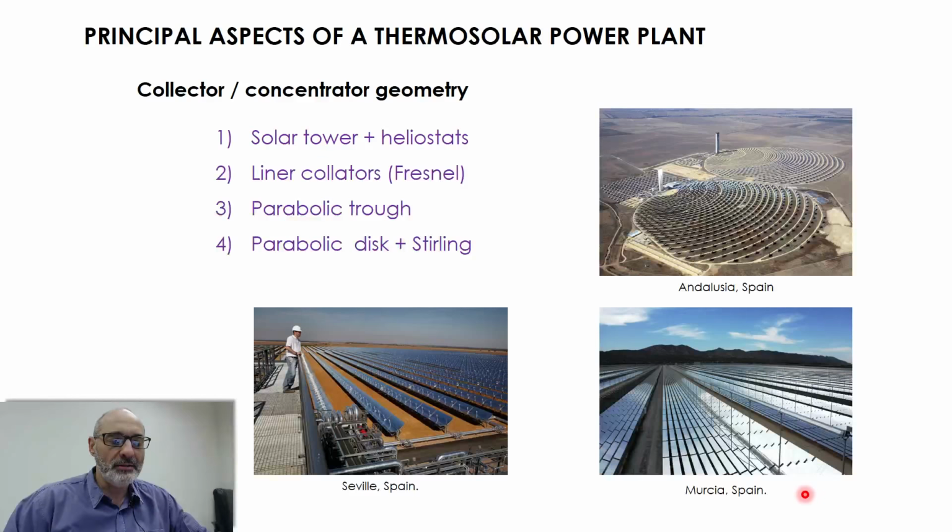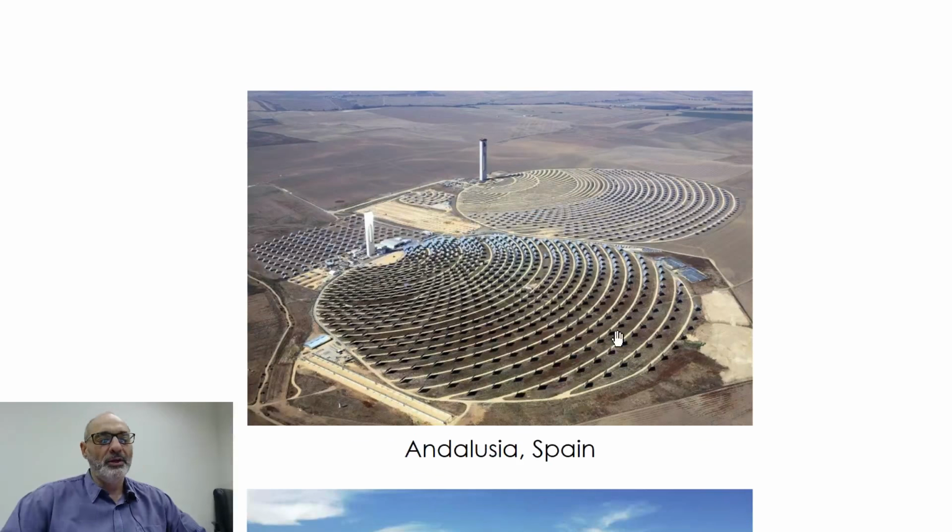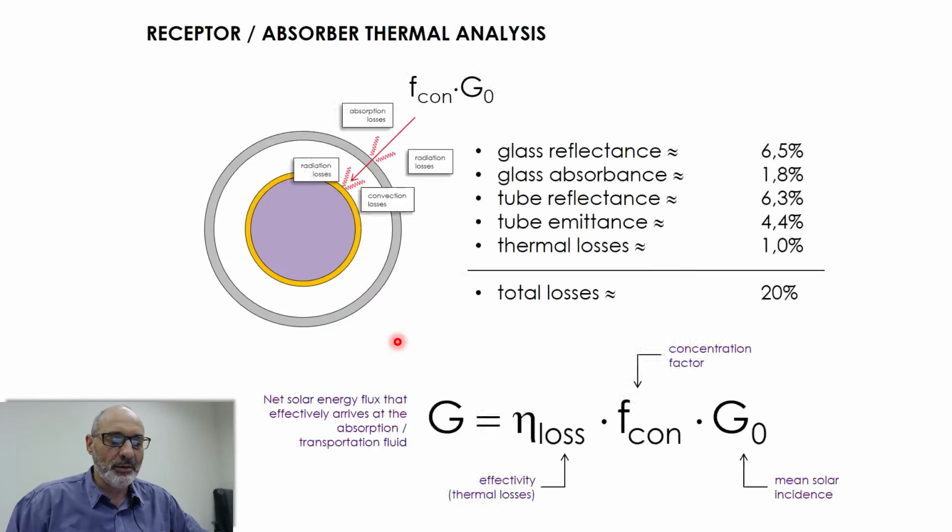They are sensitive to aeroelastic effects. I'm going back some slides just to explain this here, at our solar tower. What happens is that these mirrors start to vibrate, for instance, due to wind; the action of the wind makes them vibrate and deform. So the focal point actually becomes a blur. So you have a loss of concentration efficiency due to the structural stability of these reflectors. Okay, so that's something to take into account.